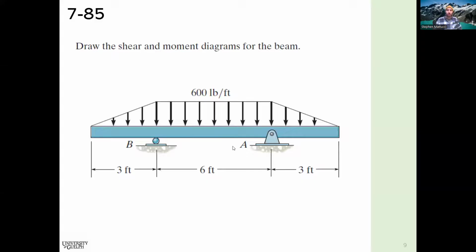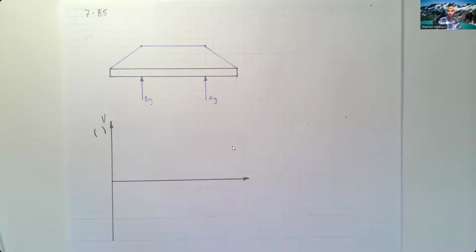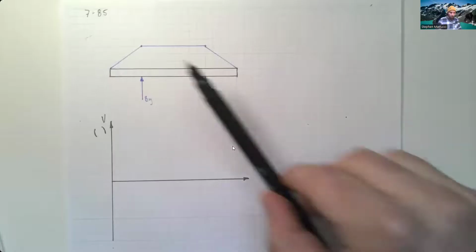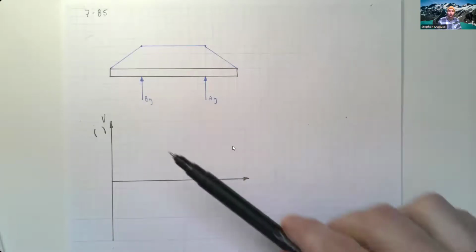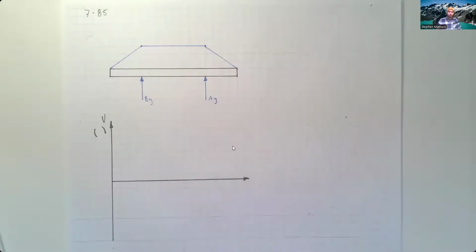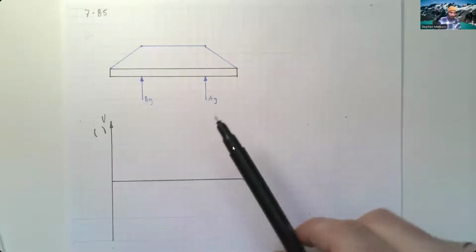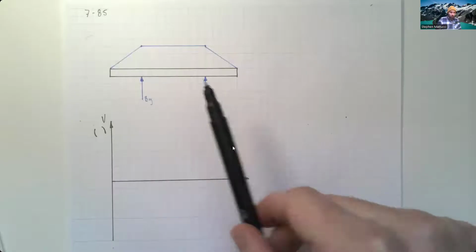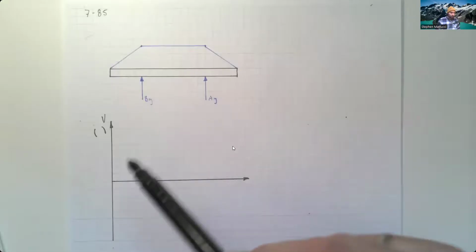So we're looking at this problem here. The first thing to do is to draw a free body diagram. So I'm going to switch over to my page. I've already gotten started here. I've got my free body diagram of my distributed load here, and I've only just drawn the hollow diagram because the first thing we're going to need to do is determine these two reaction forces. And to determine these reaction forces, we're going to represent our distributed loads as resultant forces.